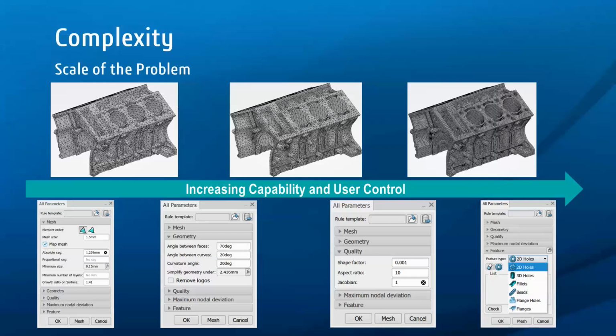The user interface also takes a designer-led approach, allowing users to delve deeper into the mesh controls as their skill levels increase. Recommended defaults can then be modified based on the user's experience. And another added benefit of the managed data model is that any mesh specification a user creates can be saved as a meshing rule. These meshing rules can then be searched for in the database and reused for other components or simulations when similar geometry is encountered. And that could be reused by the same person who created it or another person who has been provided access to your platform. A perfect example of knowledge capture and reuse across an organization.